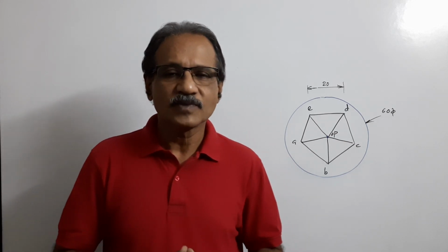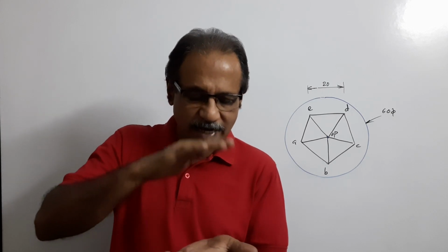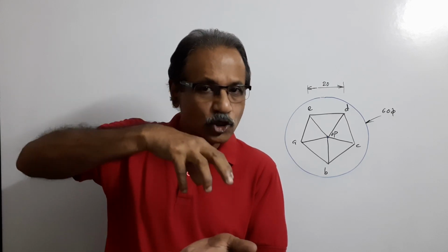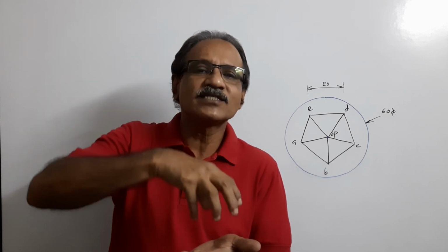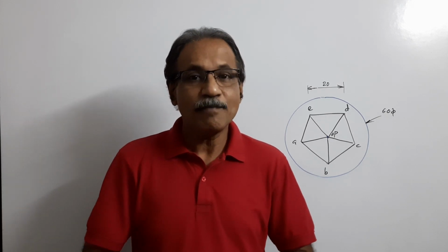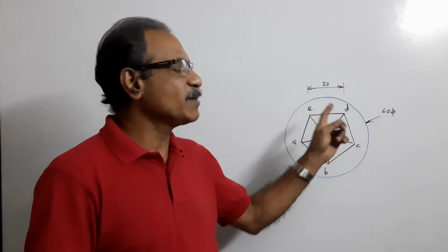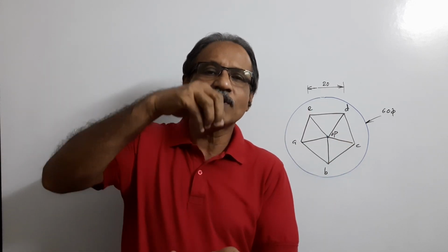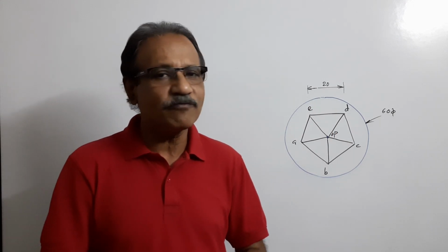I repeat, a circular slab 60 mm diameter, 40 mm thick is standing on the ground. On its top, centrally, a pentagonal pyramid is standing. The pyramid has 20 mm side of base and 50 mm axis length. Agreed? You are asked to draw the isometric view.